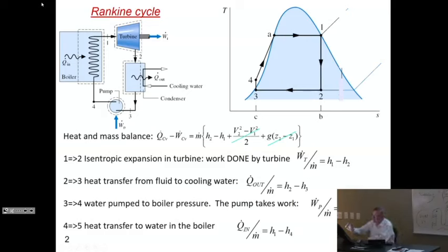This is your Rankine cycle. You take steam, which in the Rankine cycle by hypothesis is saturated vapor, at point number 1. You expand it isentropically through a turbine from 1 to 2. That does work out from 1 to 2 isentropically. This turbine then does its work, WT, so the power produced per kilogram of mass flow through the material, is the enthalpy difference between point 1 and point 2, positive. Positive because the arrow is this way.